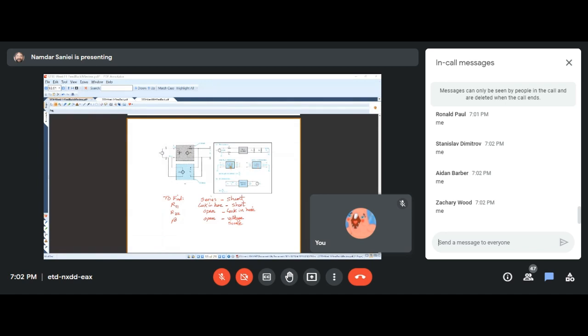And for that, R11 was H11, and for H11 we had to short V2 when we were dealing with H parameters. R22 was H22. We were looking into port 2 of the H parameters, and in order to find that, which was V2 over I2, we had to keep V1 open.